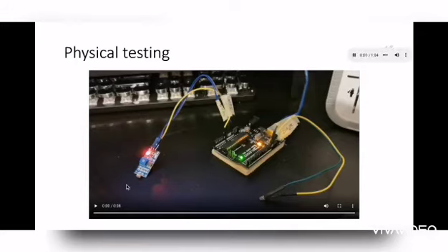After completing the Tinkercad simulation, I tested the code on an Arduino circuit board provided by the university. The board consisted of an LED, photoresistors and suitable resistances. I copied and pasted the code into the Arduino software, connected the circuit to my PC and uploaded the code to the circuit. At first I realised the code worked, but the timing between code loops was too long, so it left me wondering if it did work, but it just took a while.